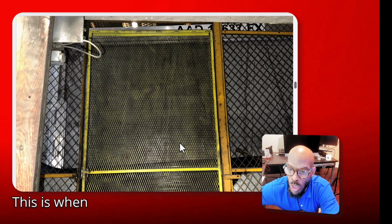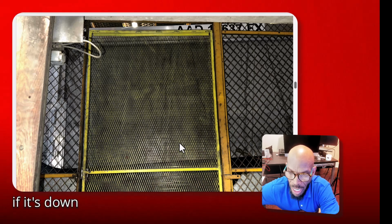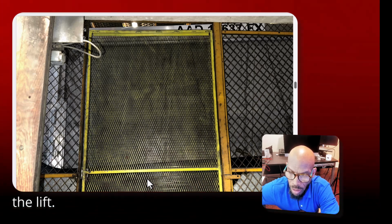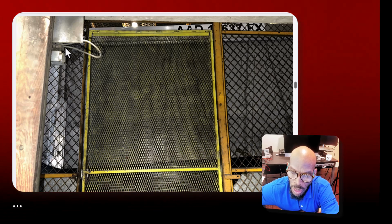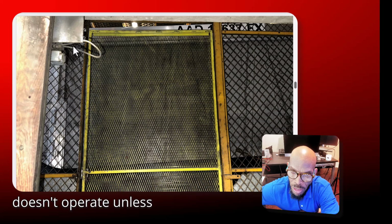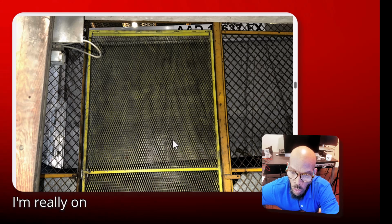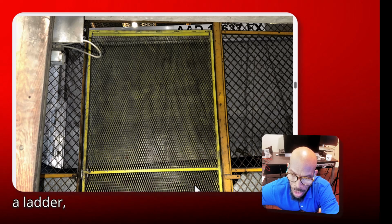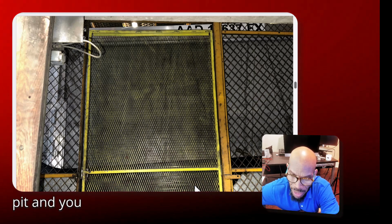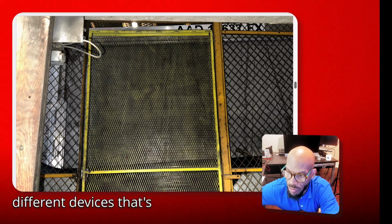This is when you walk into the equipment room. If you just head straight, you will see the lift if it's down on the bottom floor. And you can open this up and then you can go under the lift. So it has a safety switch up here, a safety limit switch. The lift usually doesn't operate unless this switch is bypassed right here when you have the door open. And this is really only for maintenance personnel. Because when you go in here, you've got to go down a ladder, and then you'll be in what they call the pit, and you can see up under the lift, and you can work on the different devices that are under the lift.